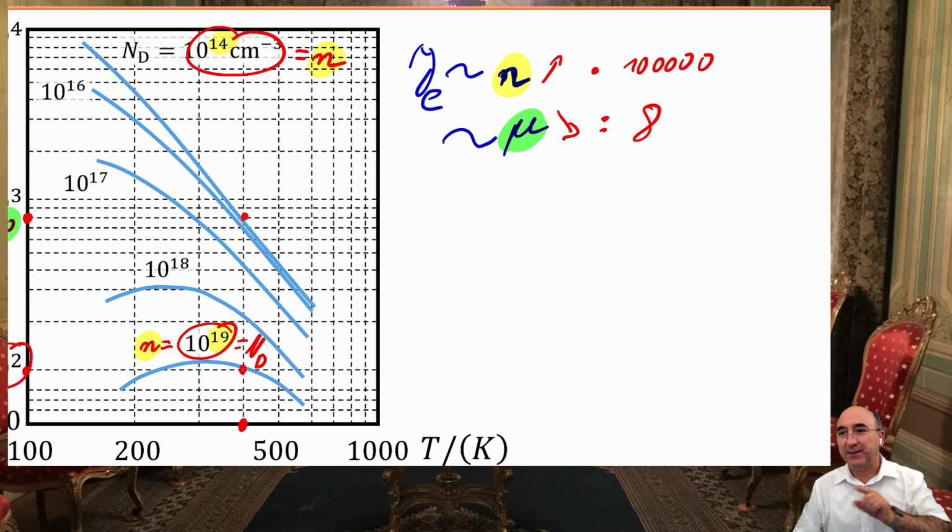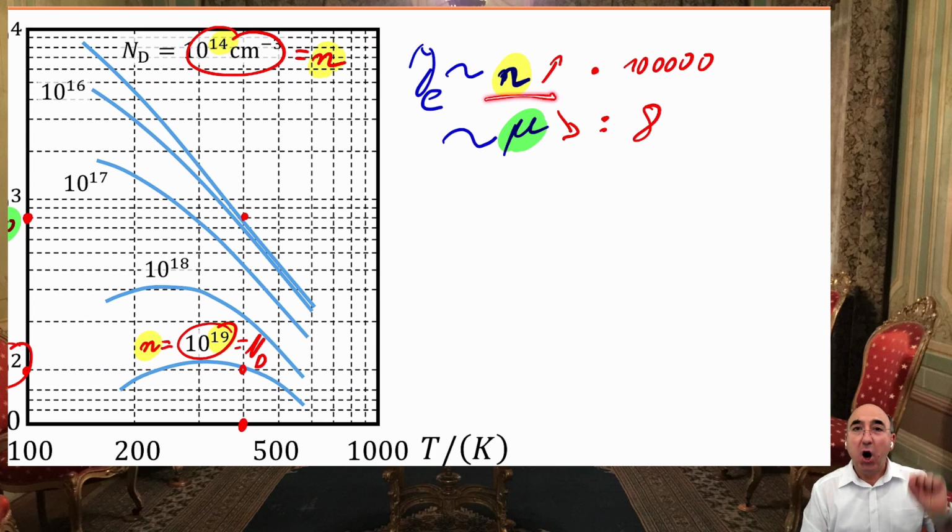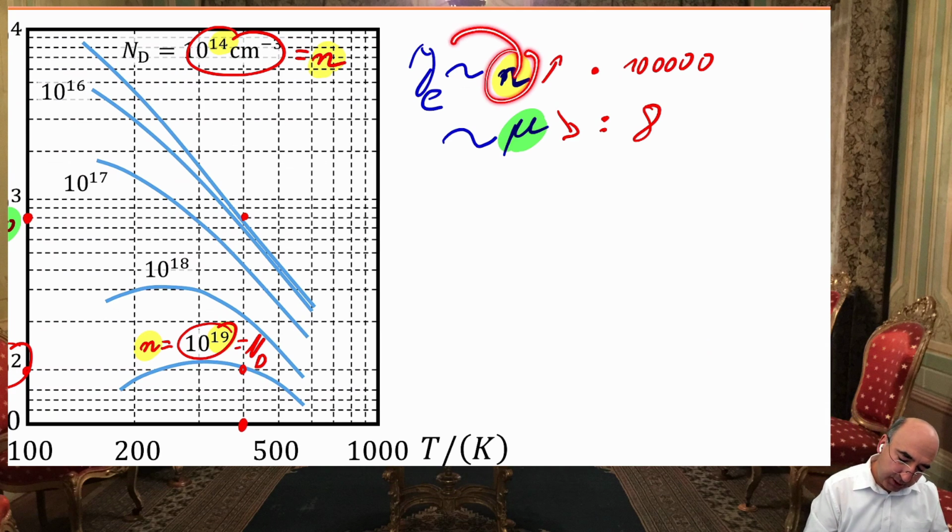You were right. If you want to increase the current density, you have to increase the doping concentration. Although the mobility is reduced, that means your increase in doping is not one by one. So the increase in doping concentration is not increasing the current density one by one.